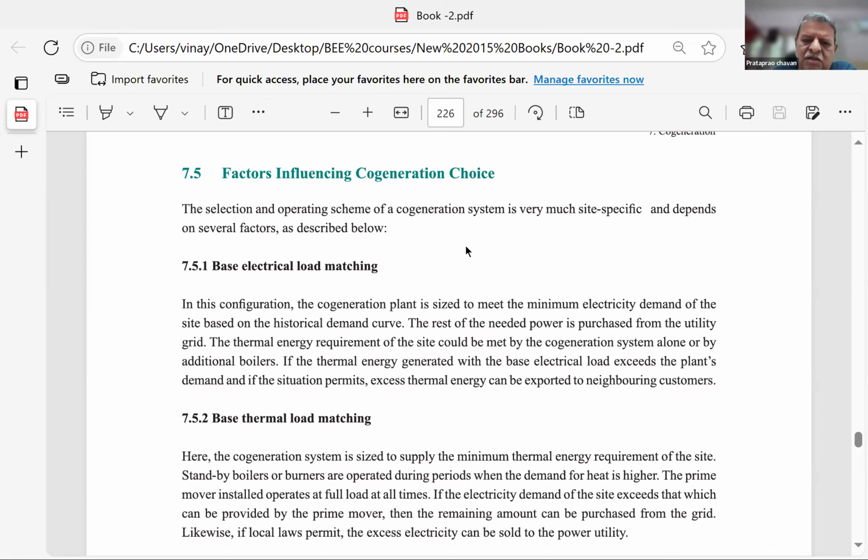That is the case for all electrical loads. As we have discussed, even the grid load is not constant. In the morning peak, it may go to 10,000 megawatt. Afternoon, it may be 9,500. In the midnight, it is hardly 6,000 megawatt. It varies. So your generation also should match your demand.